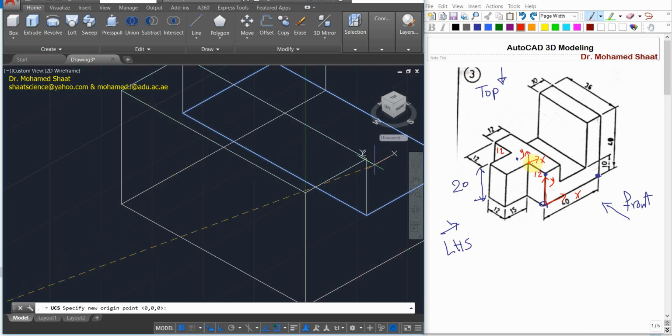But one of the points that we can define is the midpoint of this face. So instead of moving 12, this is another option, to use the things that you already have in hand here in AutoCAD: I can move this XY plane to the midpoint, making the XY plane here in the middle. Because I don't have this 12, I cannot locate the 12 distance over this edge, unless you draw a line and then remove the line, which is more steps.